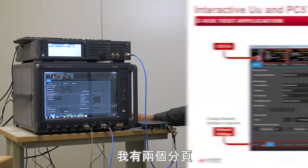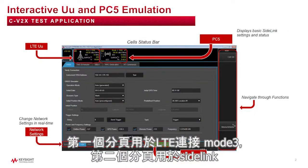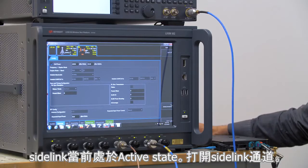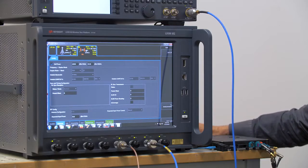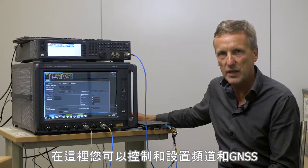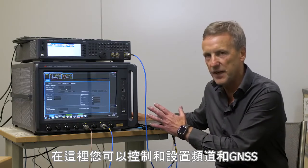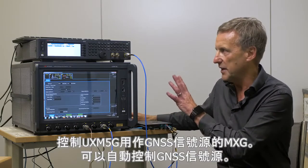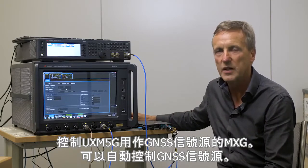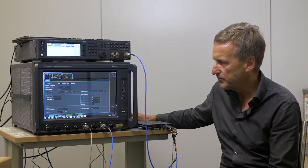Here we see we have two tabs. The first tab is for our LTE connection for mode 3. The second tab, which we have active, is our side link tab, and we can see it's highlighted. We have the side link channel on. We can see here that we are able to control and set up the channel as well as GNSS, and the UXM 5G controls the MXG for GNSS, so we are in full control right now for GNSS.